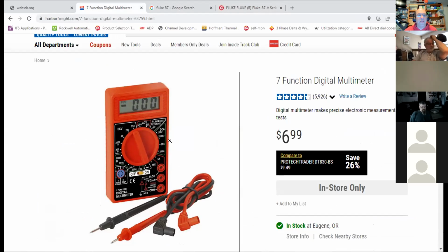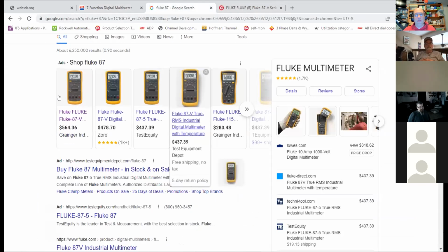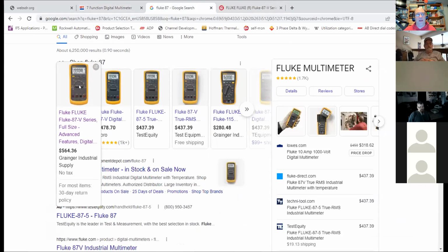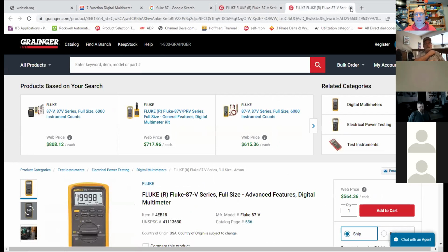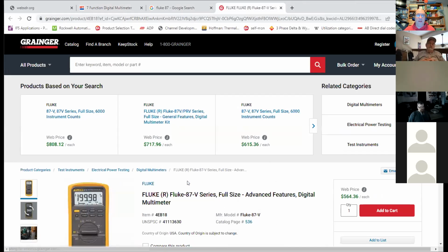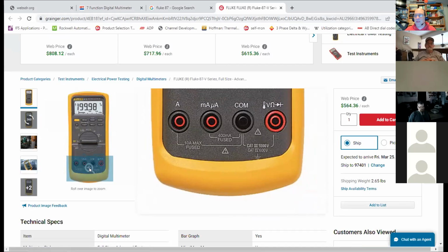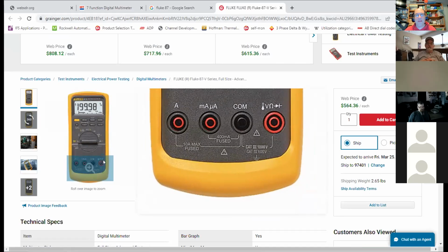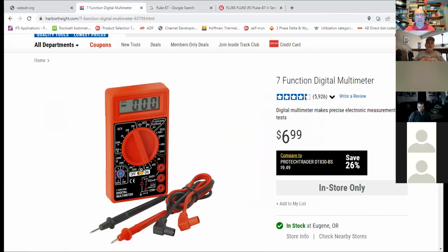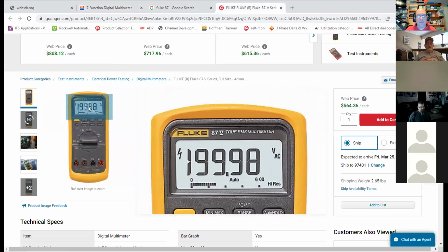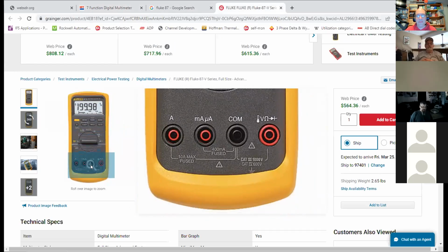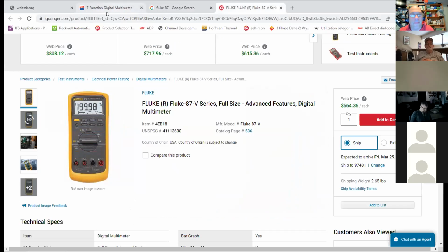And some of these small meters will actually say 750 or 1,000 volts. My Fluke also says 750 or 1,000 volts. So how are they different? Well, one of them, there's different ratings. There's different category ratings, Cat 2, Cat 3. That one's a Cat 3, the other one was a Cat 2. And so it's rated to different levels. You also need to make sure that they're certified on the back so that they don't blow up. I've seen them blow up before.